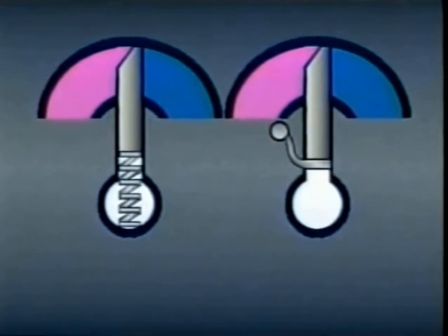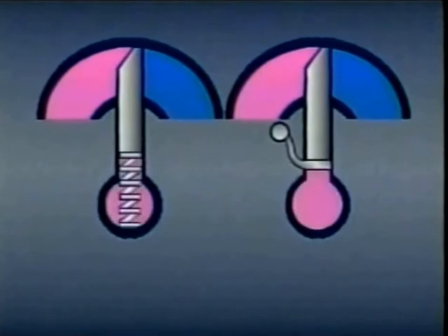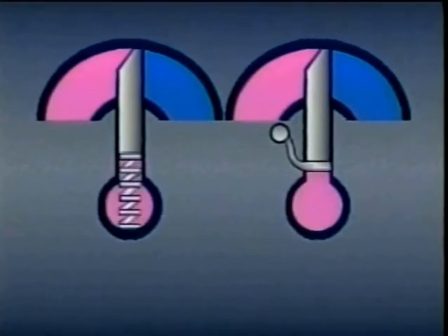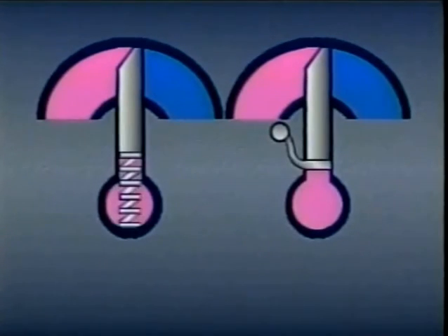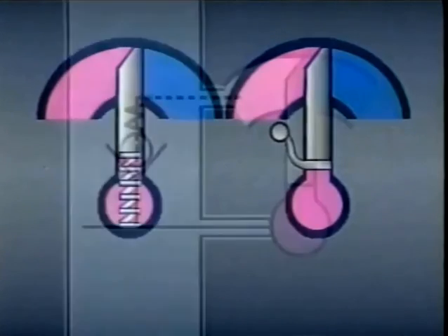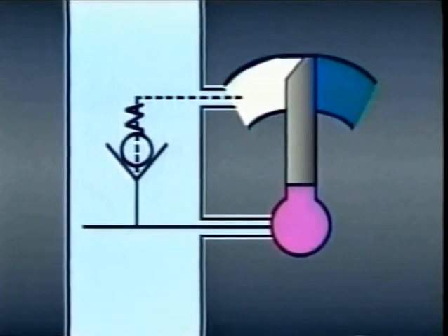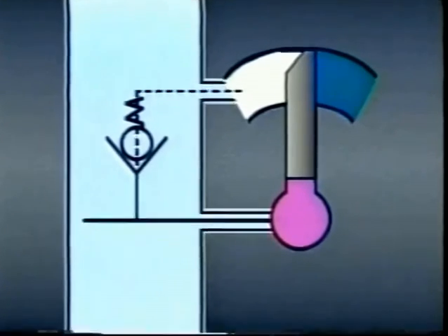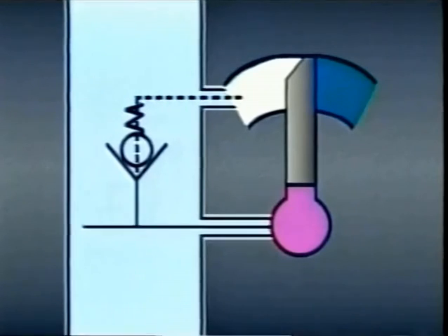In either case, once the motor is turning, fluid pressure is directed to the underside of the vane to help maintain a tight seal. Fluid pressure may also be used to force the vane out before the motor starts. This is done by using a check valve, which prevents fluid from entering the motor inlet until pressure is high enough to force the vane out against the cam ring.